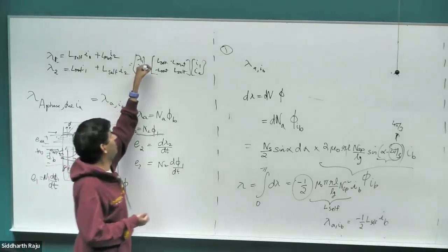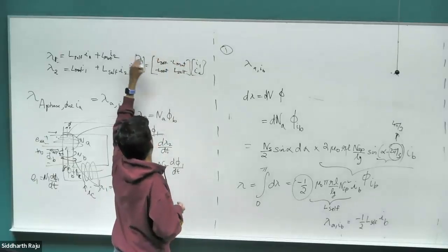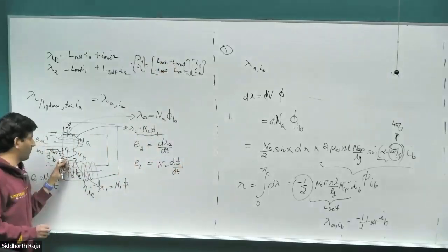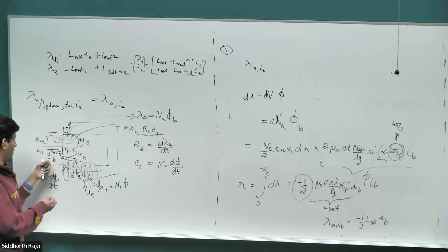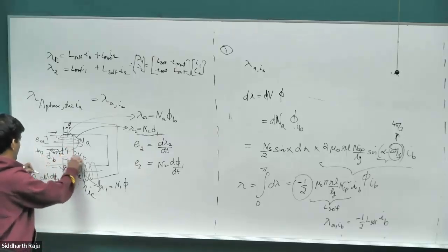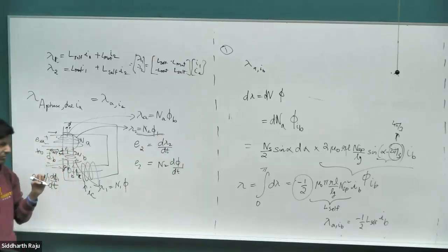Right? So that's what we are modeling here. If I pass some current, say I1, and create some flux linkage, then I2 would try to counter the flux linkage because we reverse the coil direction. The same result you could have achieved with the answer Jack gave can be achieved with the answer Hannah gave, which is basically keep the coils as they are, why complicate life, and just reverse the direction of the current, either of it, the same.